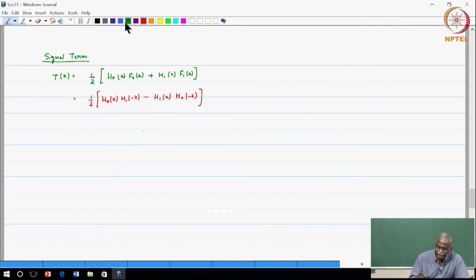However, we are going to take a very general approach where we say that okay, good that we got T of z. If I look at it as a frequency response on the unit circle, I can write it as the magnitude of T(e^{j omega}) times a phase term. Okay. So, this is nothing but the magnitude response of the transfer function.